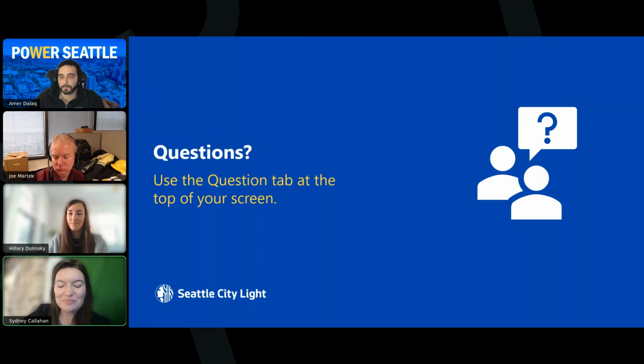Thanks, Amer. Another question I see: folks are hearing about long lead times for some transformers. So the question is, how is that impacting City Light? Yeah, so we still have long lead times for certain transformers. The residential ones, not as much. The overhead pole mounted transformers, we have those in stock. The longer lead times are for our CS units or our pad mounts, so the larger transformer services. We're still about 2 years for lead time for those. Most likely it won't affect most of the DERs, but in certain scenarios it could.